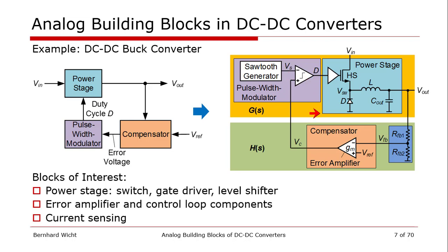So that altogether has to be stable under all conditions, of course. And we see already a lot of building blocks which are of interest and which will be addressed during this talk. So it's the power stage, switch, gate drivers, level shifters, and then in the control loop, error amplifier and various other components, including protection and also current sensing.